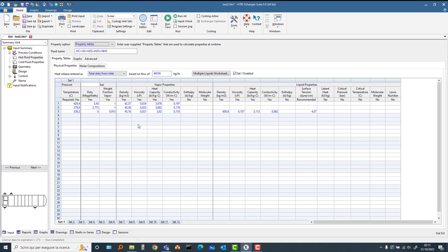Since the pressure has an influence on this curve, we should need at least two curves, one at the inlet pressure and the other one at the outlet pressure. But nobody knows, at the beginning, when starting the calculation, how high the pressure drops will be.